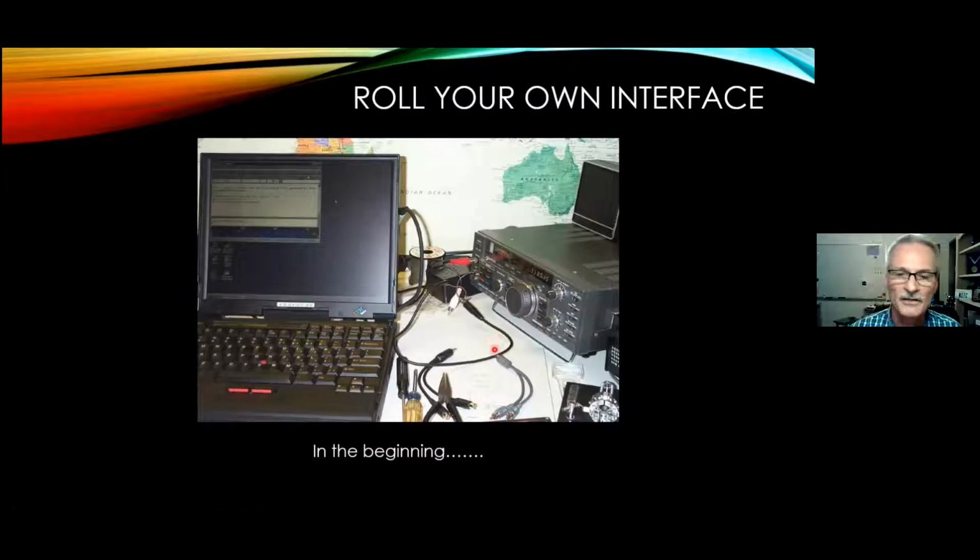And you can see this is really ugly. I took the headphone jack here and ran it into the audio in on my computer. I took the speaker output from my computer and jury-rigged some resistors in here to drop the level down a little bit, and then shoved it into the microphone connection here. And, believe it or not, I made many contacts on PSK31 with that messy setup. It did work.